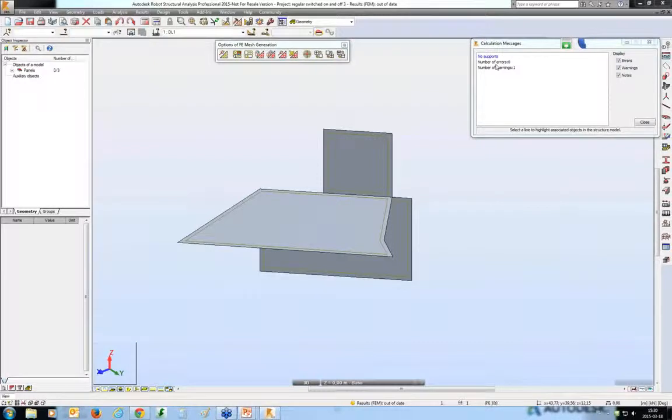Otherwise, I would define the structural axis at the characteristic points of the model, like along the walls, at the level of the slabs, and then I would correct that. That's the first model that we covered during the presentation. Then if you update the Revit model, you will update the analytical model corrected in Robot. So there should be no further issues with that.